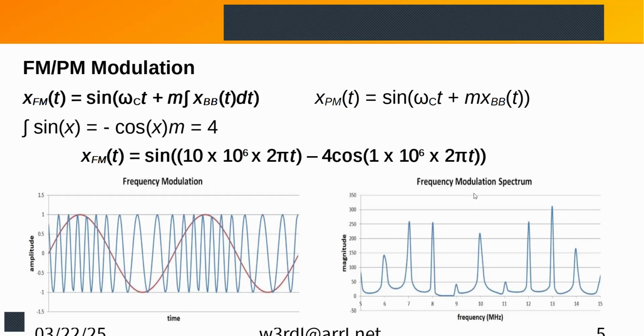If you look at a spectrum analyzer, you're going to see this kind of a frequency spectrum, and you're going to see these harmonics of the baseband out here on either side of that fundamental. Similar to what you would see if you look at an AM, where you see the sidebands. In FM, you see multiple.